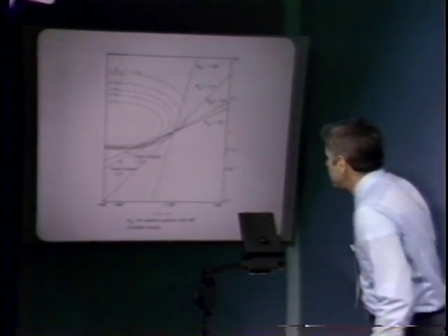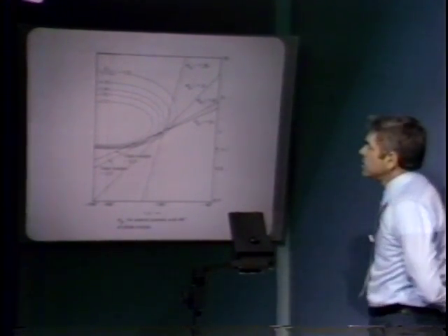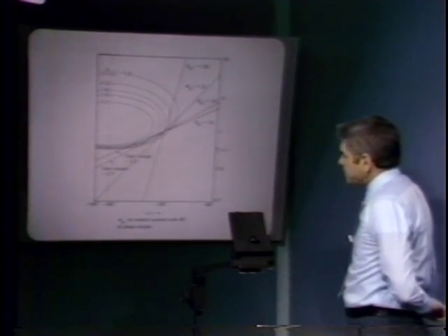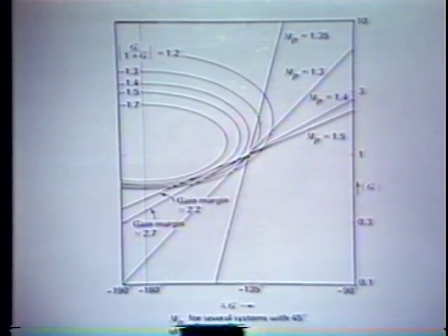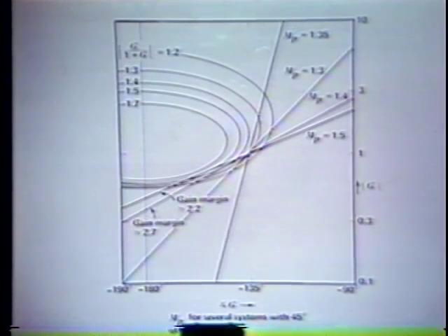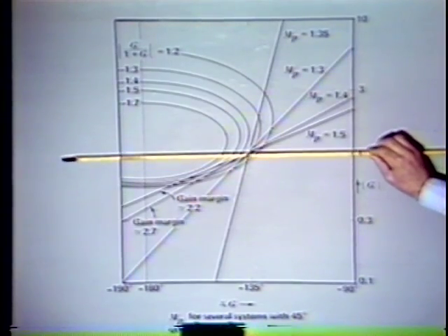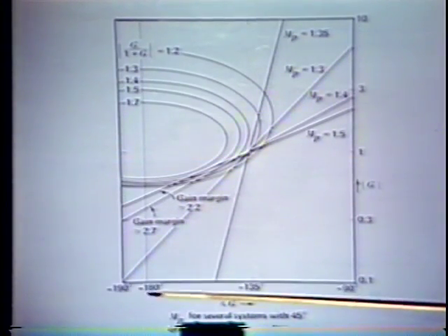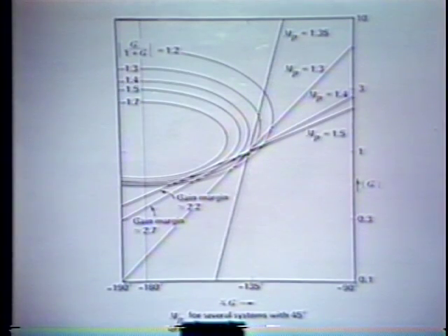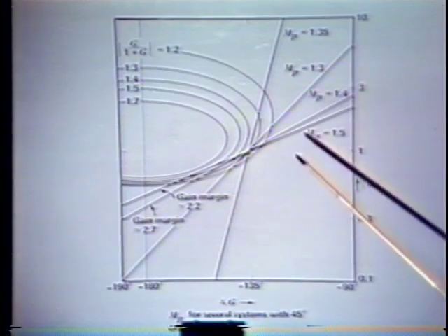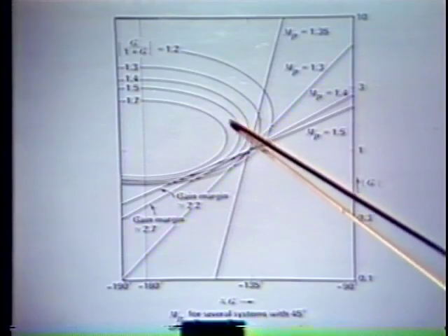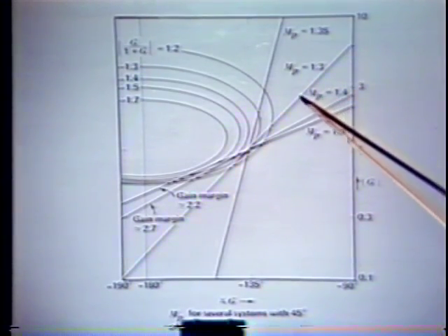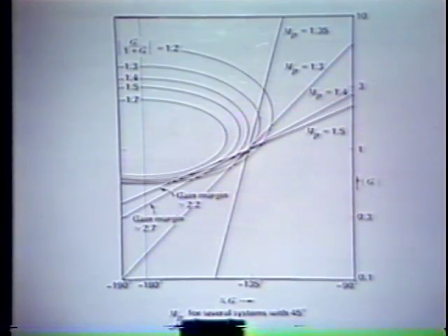Here we've shown a much simplified Nyquist chart and eliminated a lot of the additional contours that confuse the issue. And we focused once again on the magnitude equals 1, angle equals minus 180 degree region of the Nyquist chart. And what I've assumed is that there's a straight line relationship, in this vicinity at least, between the magnitude and angle of the AF product.